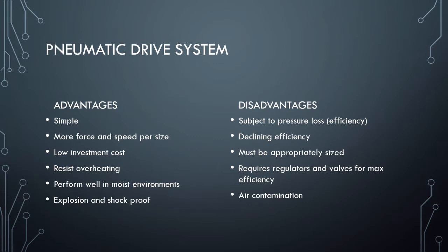What that means is you have to make sure that you have enough of an area to fit these in. Essentially, they can be a little bit bigger than an electronic drive system, so they have some larger size requirements. And then you have to make sure that the drive system is sized up to account for that loss in efficiency. They also need some additional components, so you have to add regulators and some more valves to try to boost that efficiency. And they're subject to air contamination. That could potentially be an issue with these drive systems and cause more maintenance problems.